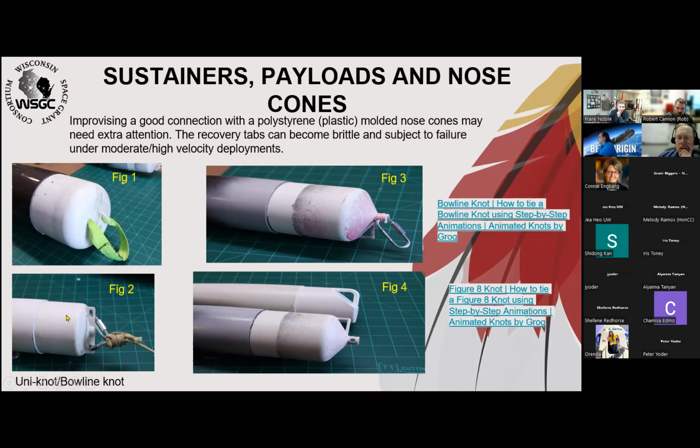Of course, we have a different design here, a bulk plate nose cone with 2 holes on tabs like that. Double it up. It's best to double it up. Also, if you desire to, I'll show you in a different picture. Of course, these are the tabs that come in. Some model rockets do not use these tabs. They will snap off under certain velocities if your rocket is coming in hot, or at a high velocity during your main deployment.